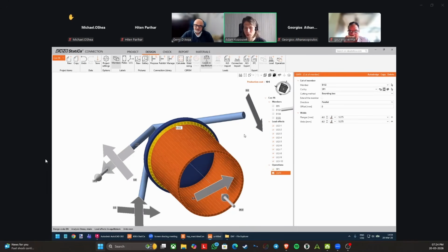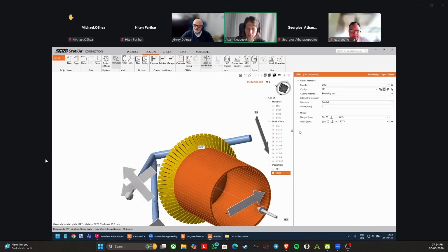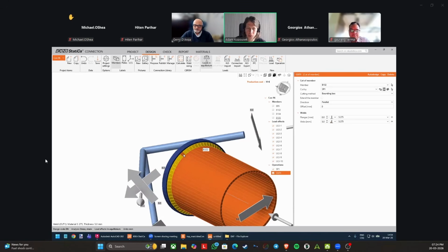What I like to do is change the thickness. There are no flanges for a tube, so I turn this off. It was already turned off, obviously, but I'm very punctual, so I want to have this perfectly nice. And here I simply change the weld thickness. So I'll choose a 5 millimeters weld, and I can also choose the material of the weld.